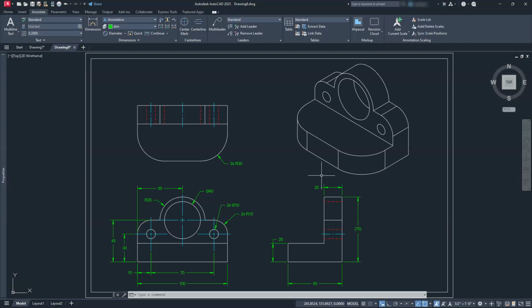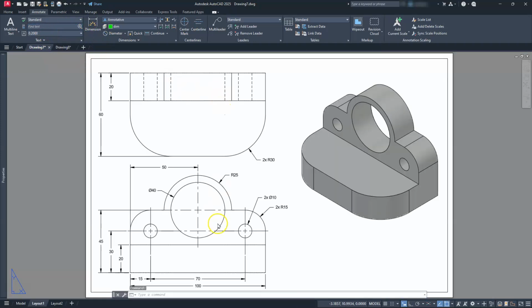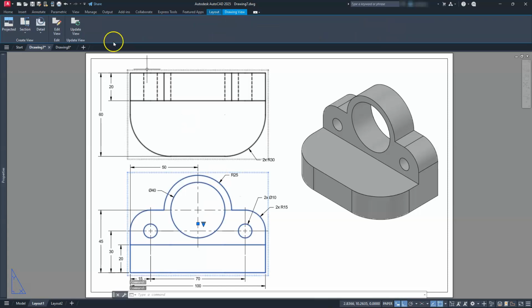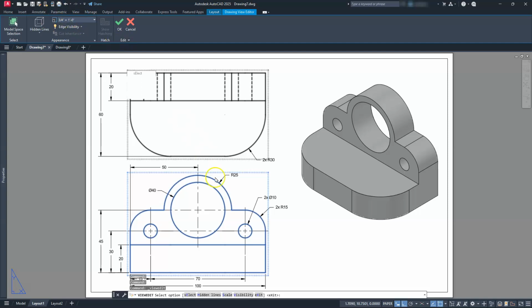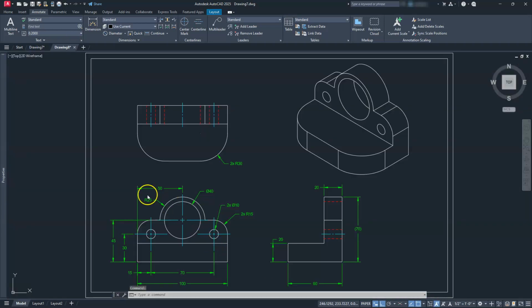And also, if you can remember what I said before, tell me what, and I forgot about the scale of it already in this one. Let's see, I think it was 3/4. Yes, it was 3/4 equals a foot. Let me know in the comments below what this scale factor is, right? And just like in the drawing that we just did, we figured out the scale factor here was 20 or 24. Oh, 24. Okay? So if you can use that same logic to produce that, that'll help me out a lot. And if you don't know it, let me know also in the comments, and I'll make a video dedicated to just showing you how to calculate scale factors and where this stuff came from.